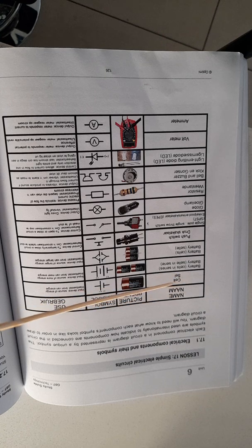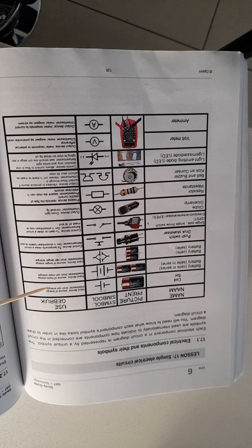The first component is a cell with a C, okay? Using English, so the cell with a C. So this is normally what we call a battery. So from now, don't call it a battery, it is a cell. And the symbol, okay, it is a short stick and a long stick. They are connected by lines, and the short stick is a negative connection and the long stick is the positive connection, and it is the input device. You must know it is the input device.